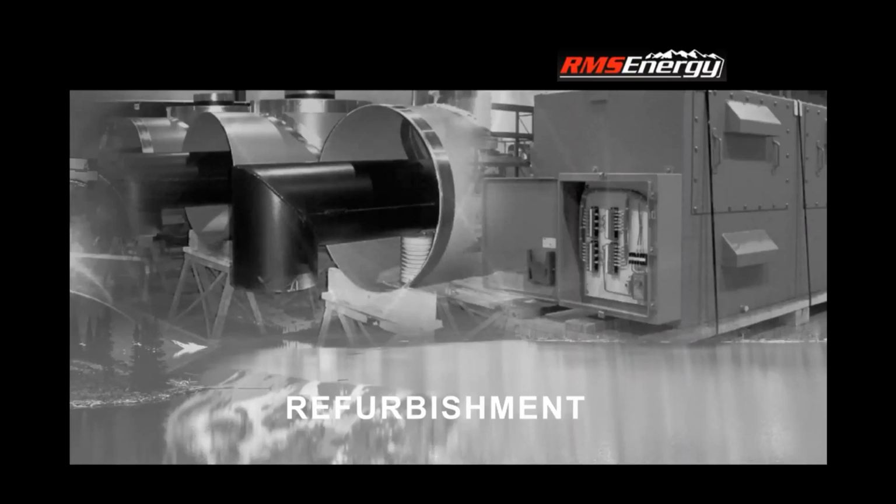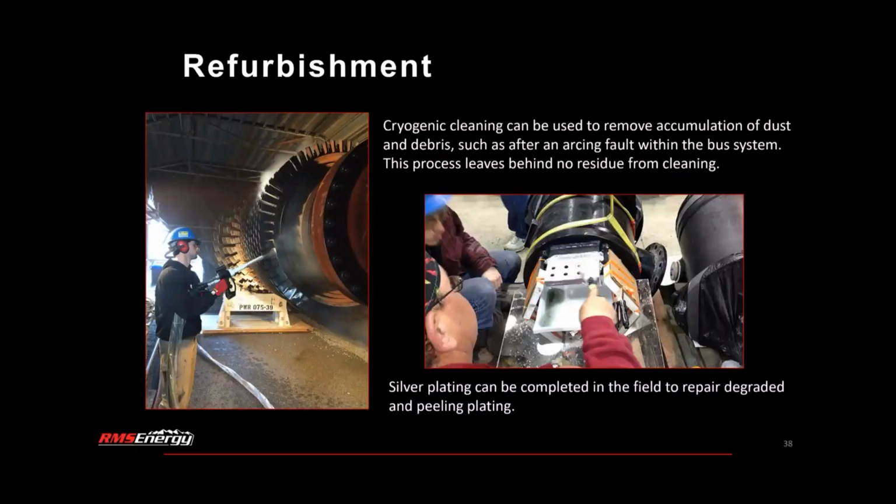So if you are already performing inspection and maintenance, or you go into your first inspection and maintenance outage and find significant problems within your bus duct, there are some options for refurbishing that bus and extending the life of that equipment. Some examples: cryogenic cleaning can be used to remove accumulation of dust and debris in a bus. This is also common practice if you end up having an arcing fault somewhere in your bus system or your termination that fills that bus with contaminants and carbon debris. If your silver plated contacts begin to degrade or flake or peel, those can be replated on site.